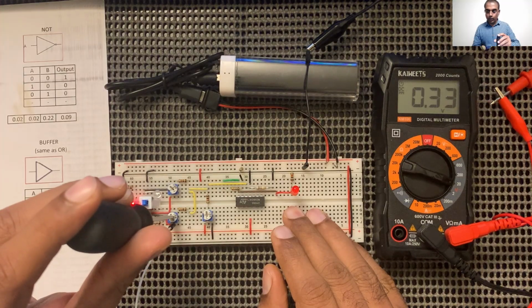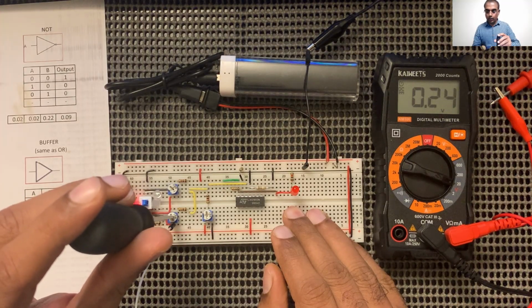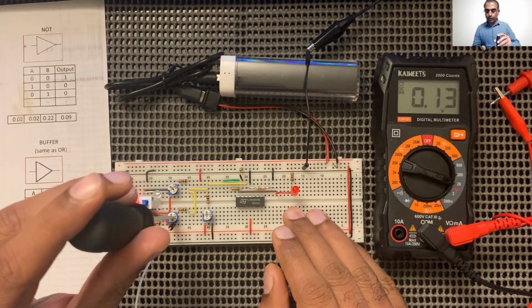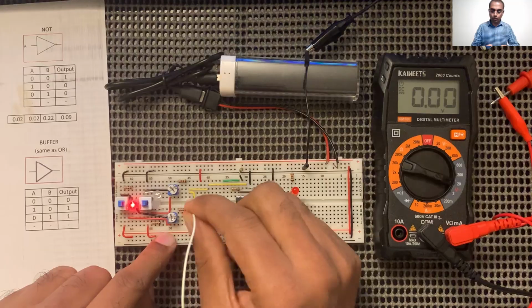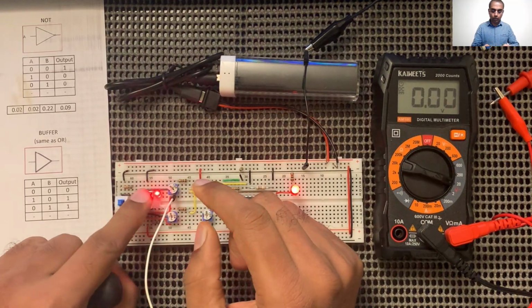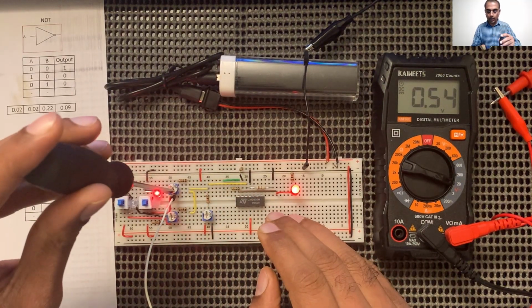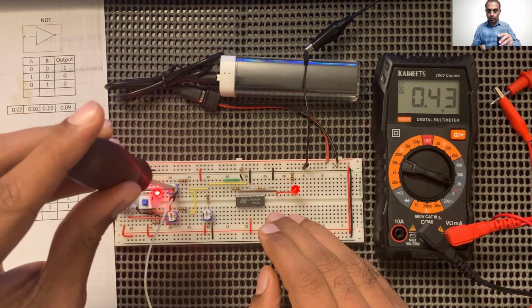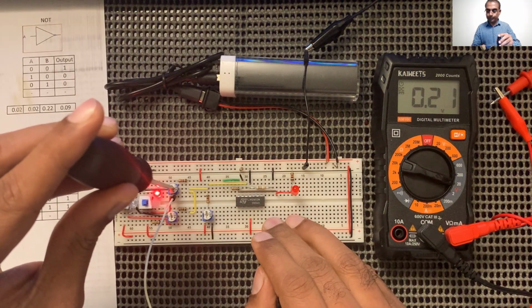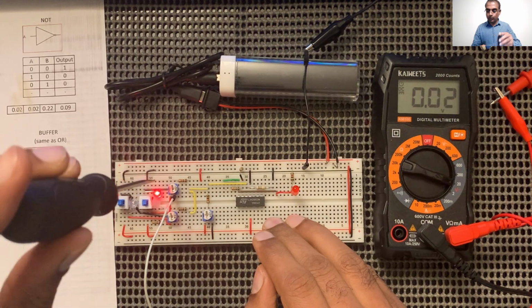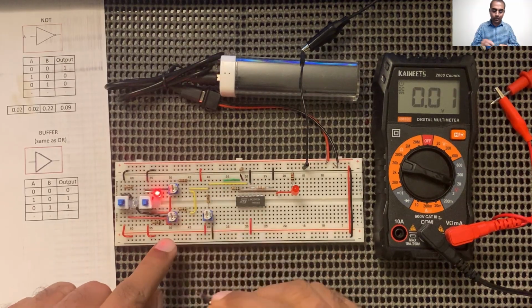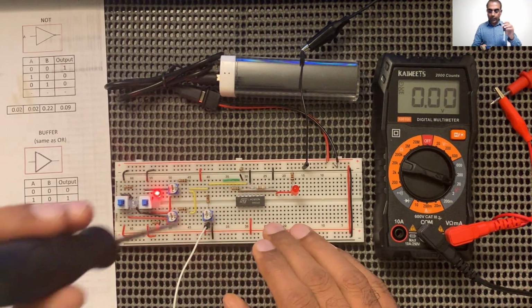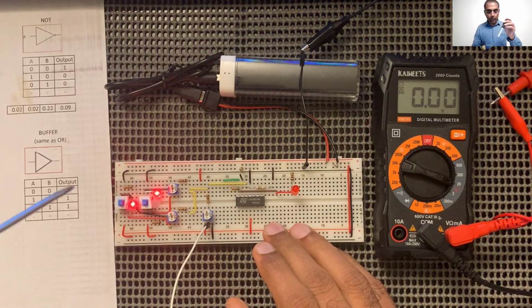I'm tuning it to the right and we can see the LED powering off, and okay, that's 0 on potentiometer A. Now I'll go to potentiometer B and start tuning this potentiometer. Okay, it's 0.01, which is closer to 0. I think that is sufficient. And now the bias should be 0.22.